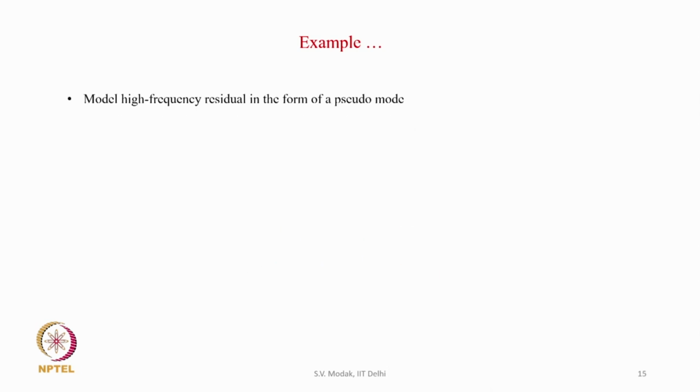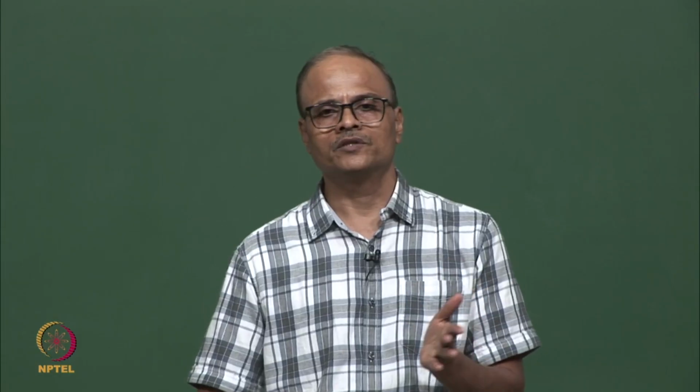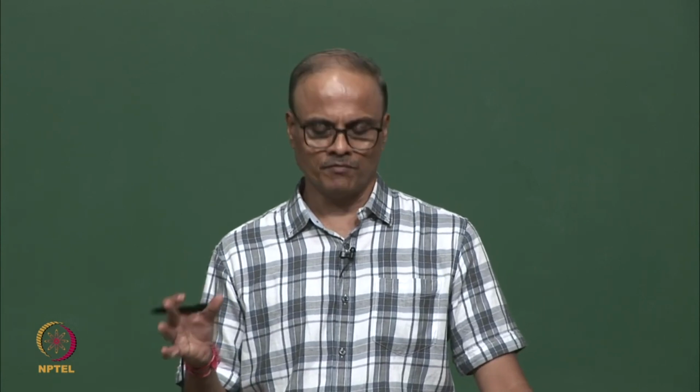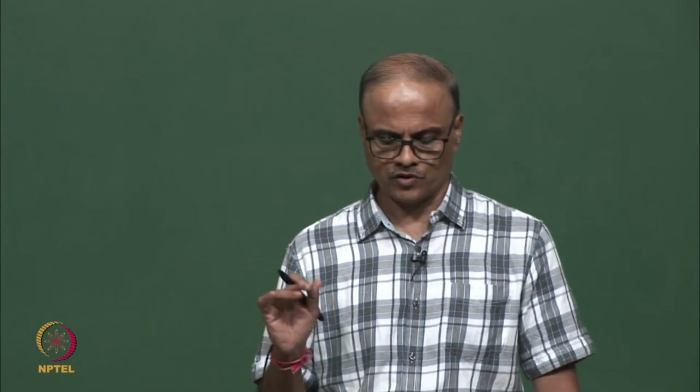And now let us also model the high frequency residual, because we see that the lower limit of the frequency band we have chosen starts from 0. So, there is no mode to the left of this frequency band, so there is no low frequency residual. But on the high frequency side, there will be some modes beyond the selected frequency band, and we would like to incorporate the contribution of those modes in the curve fitting process.